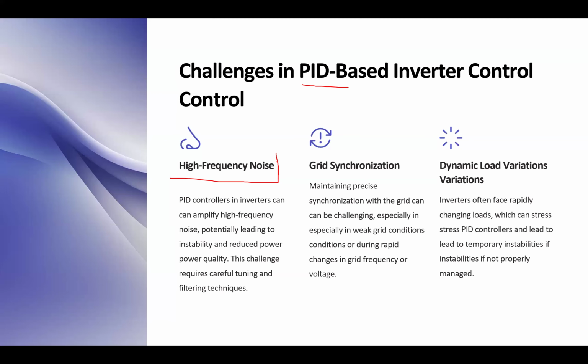And most importantly, voltage and current are tuned with the frequency of the grid, so your measurements should also identify that frequency and get tuned and synchronized with it. Otherwise, the unsynchronization effect would be translated to a higher error value for your PID controller and basically misguide your system toward a different correction value.